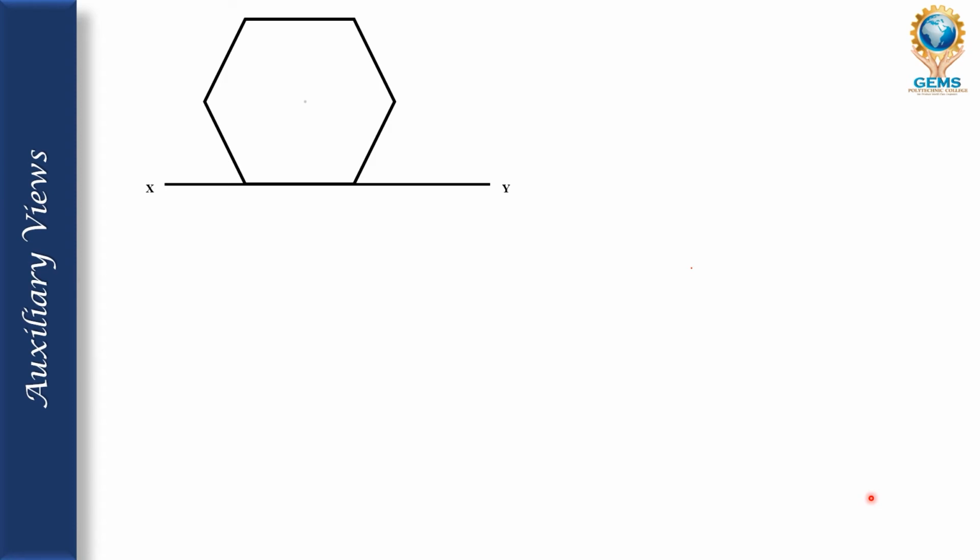After drawing, put the center line. This is the vertical plane, or the front view, and the bottom will be the horizontal plane. Now start to draw a line from the top. See one thing which is given: the details about what is given must be the main thing. From top to down, draw the center line of the object. Then again from top to bottom, draw a straight line. And now here we are going to draw the rectangular faces of the hexagonal prism. There are 6 faces, but we can see only 4 faces. So the drawing will look like this.